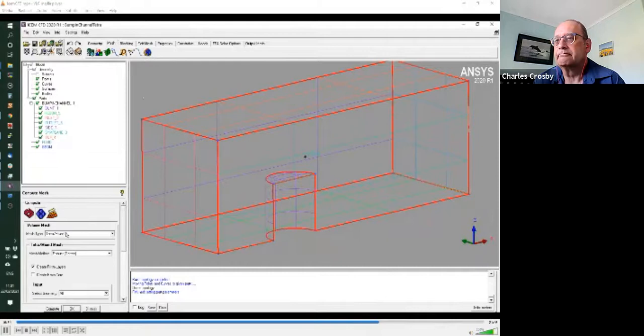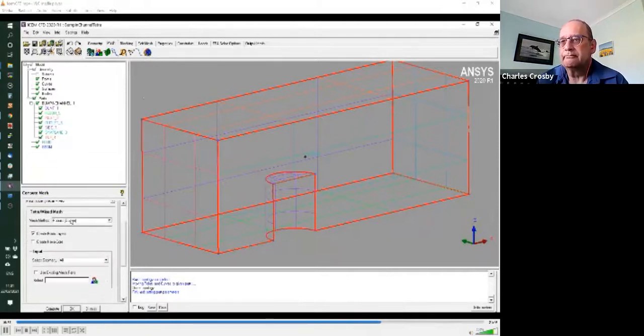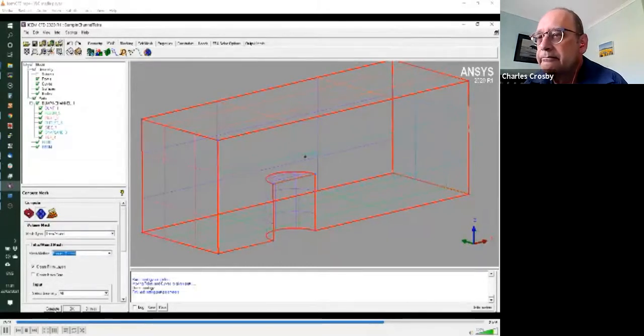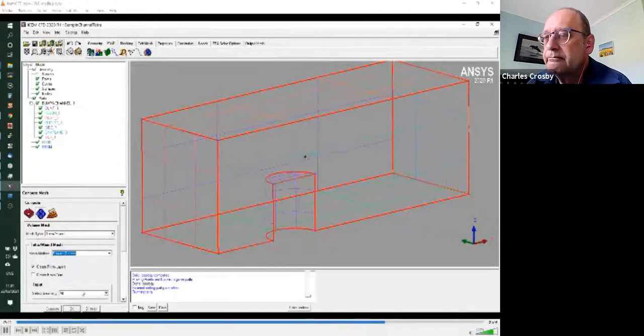We're telling it we want a mixed tetra mesh. It uses the octree approach towards generating the mesh. There are others which may give you smoother meshes, and it should create the prism layer. So everything is set up, and we can tell it to go and do the work.